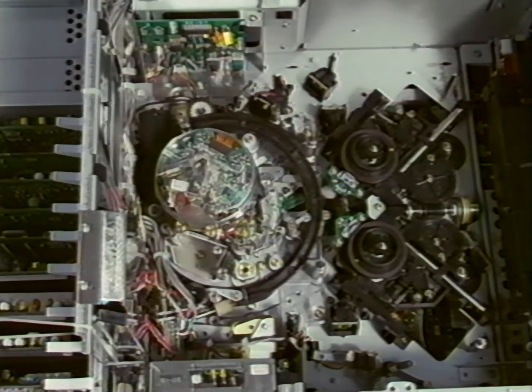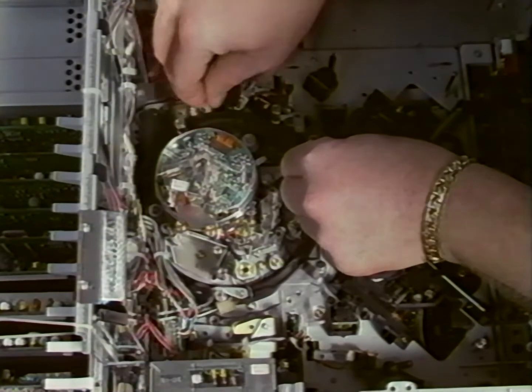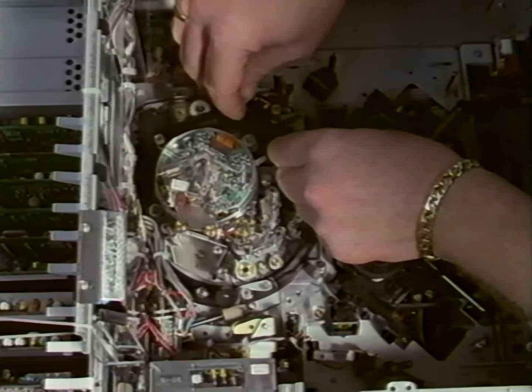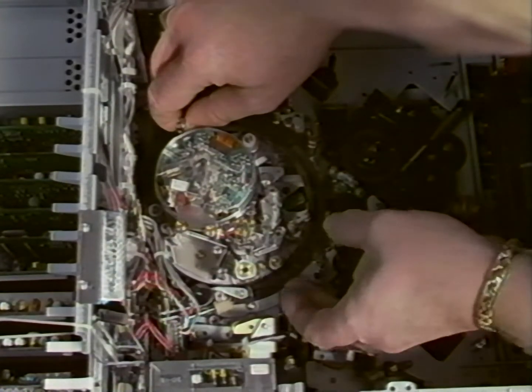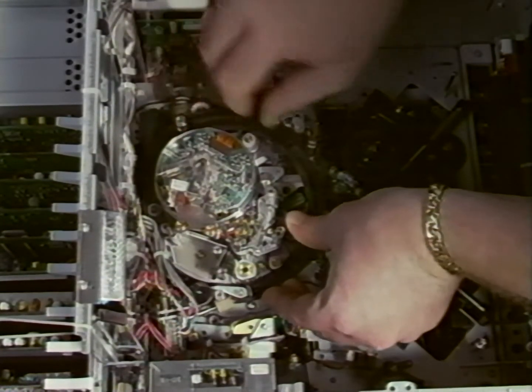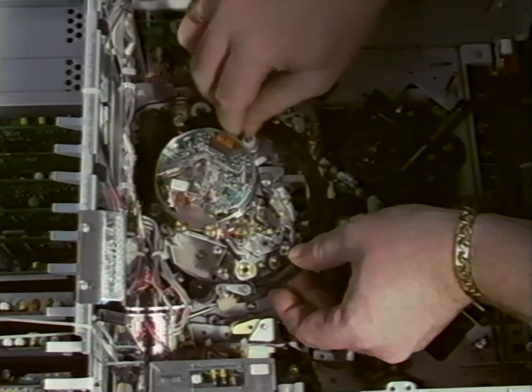Supply tension arm assembly. This procedure can be accomplished as described in Section 515 of the Service Manual, but the videotape demonstrates removing the complete tension arm assembly with the threading ring removed from the machine instead of just lifted up to gain access to the TR block. You may do this either way.